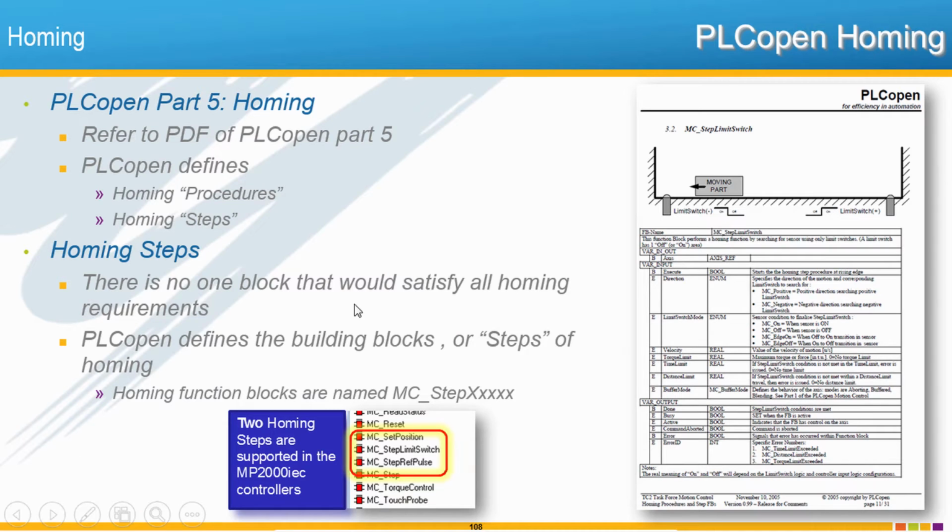And the thought with these homing steps is that there's not just one block or even a set of blocks that would satisfy all homing requirements for all machines. PLCopen is just defining what are the basic building blocks or the steps of homing. And those are called MC step in the PLCopen Edit Wizard.